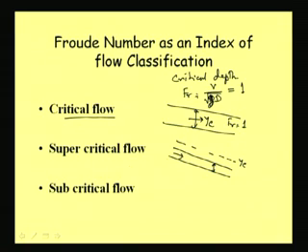Now, generally the term super comes when something is more, but here when depth of flow is becoming less than critical depth, we are saying super. Why? Because basically we are naming it in terms of the velocity here. The velocity is more than the velocity of the critical flow. So if I write velocity in critical flow, then this velocity will be more than that. So that is why it is called supercritical flow.